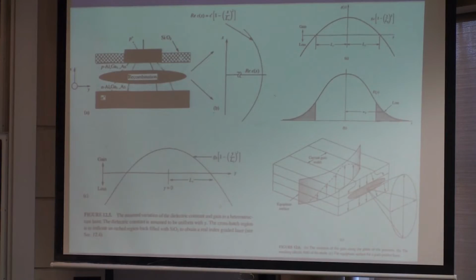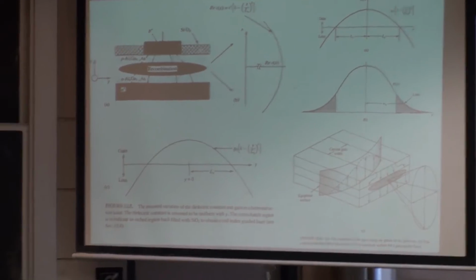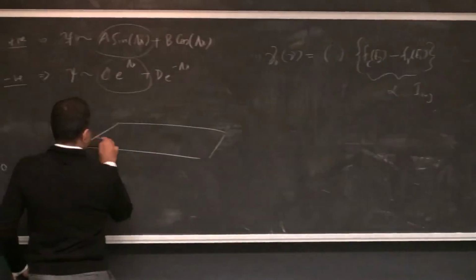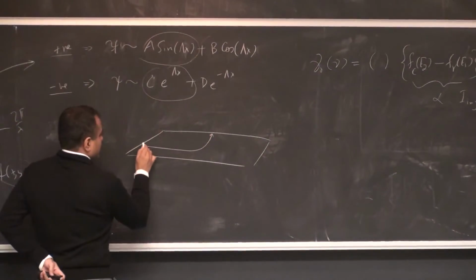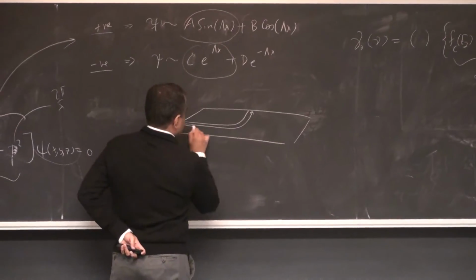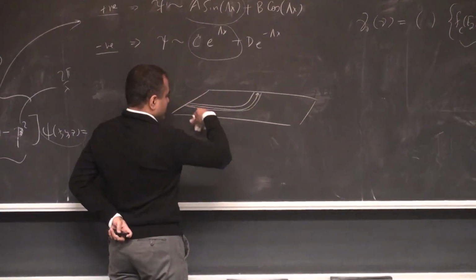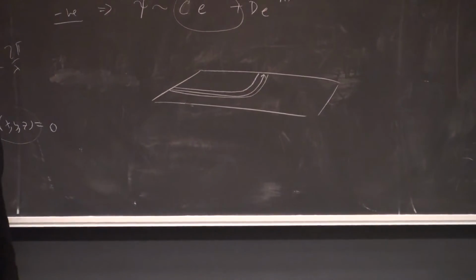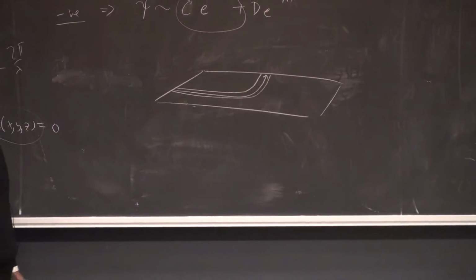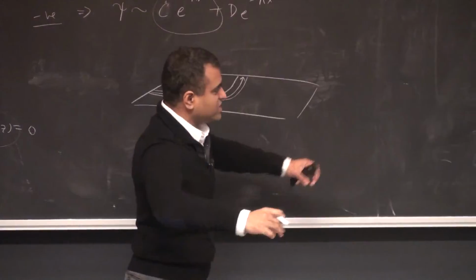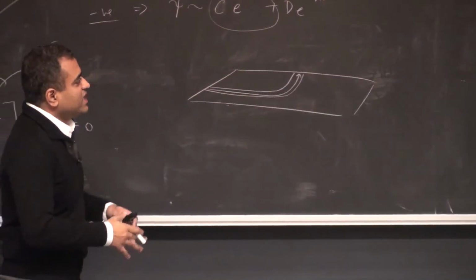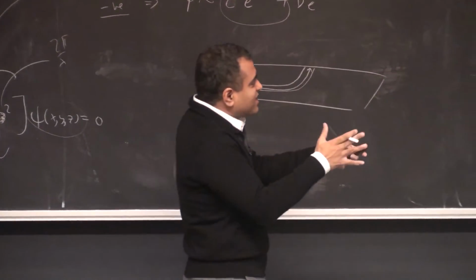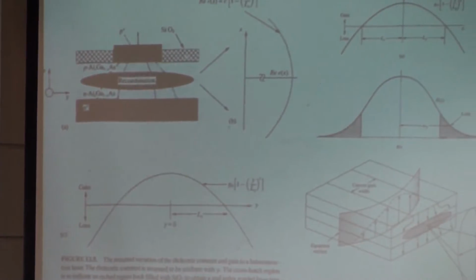For example, on the top of a wafer, if you want your light to go in this way, you can put down a strip contact and inject current in that direction, and the light will flow that way, because this is called gain guiding. And in a laser, essentially you form a long strip. But as you inject more current, the current starts spreading out a little bit further, and so the beam also spreads out a little bit.